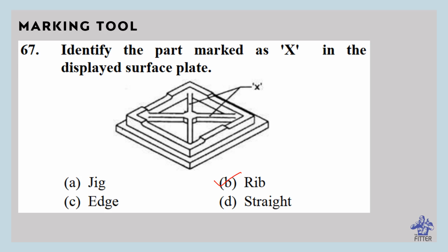It is made of cast iron, granite, or glass. Its upper surface and sides are accurately finished by scraping. It is used to test the flatness of other surfaces or to provide a truly flat lateral surface in marking work.